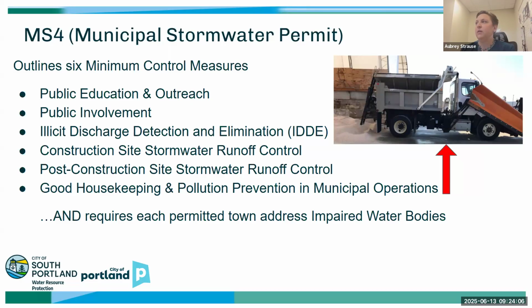The photo on this screen, I put in, I didn't even tell Doug I was putting this in, but it looks familiar to him, I'm pretty sure. I mentioned that something all the MS4 communities have to do is work with our public works departments to educate the drivers about good practices: when to sand, when to salt, when to pre-treat, but also make sure that our trucks are calibrated so that the driver knows that when the truck is on a certain setting, they know how many pounds of salt per lane mile are being put down.